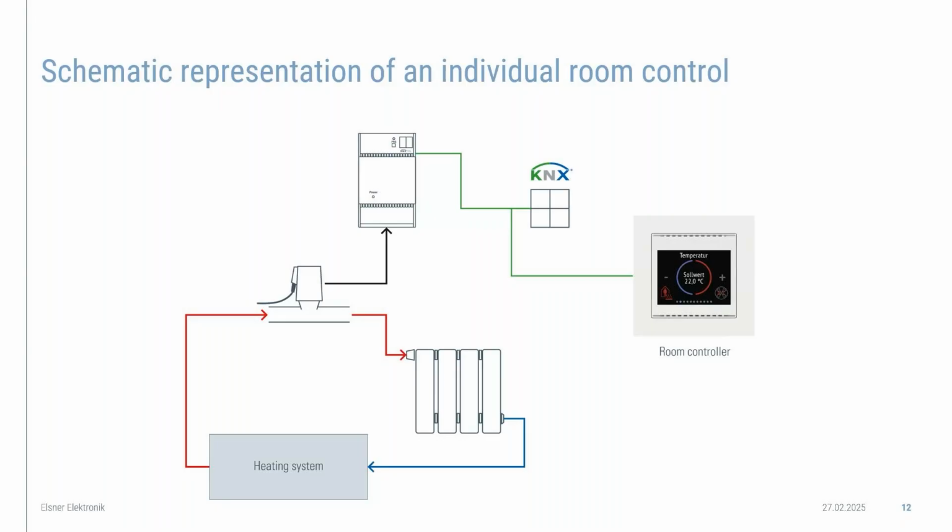For example, the actuating value is sent in percent to the heating actuator via the KNX bus. This opens and closes the actuator or the valve depending on the controller specification. As a result, the radiator emits its heat to the room. The room temperature is therefore always adjusted to the desired set point temperature.